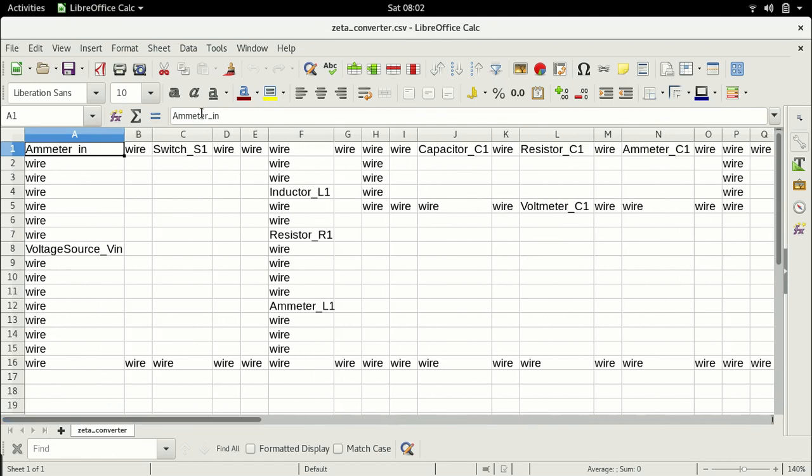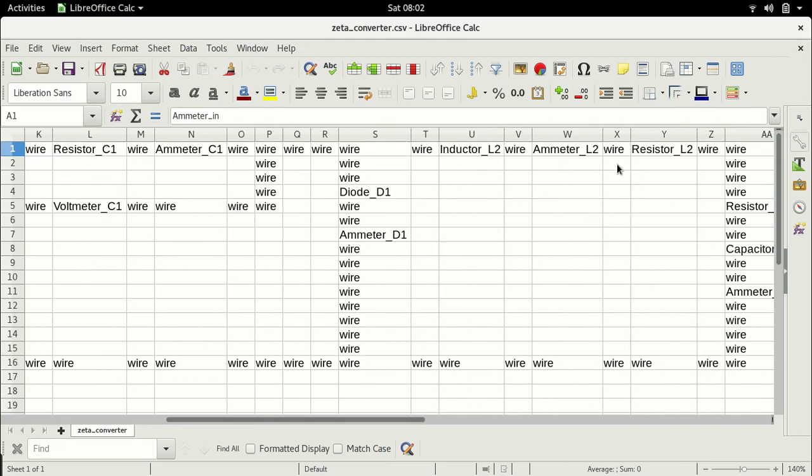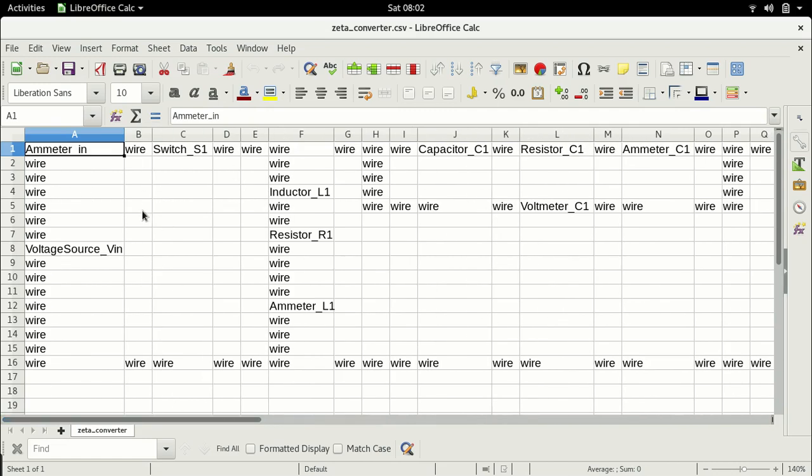Now, when we turn on the switch for the first time, you have a path in the clockwise direction, and you have another path through the voltage source, the switch and the inductor L1, and you have a larger path in the forward direction through the capacitor, through the second inductor to the output voltage, right? Now, the first path is fairly easy. When the switch is turned on, the entire voltage appears across this inductor, right? So the voltage across this inductor is equal to the input voltage.